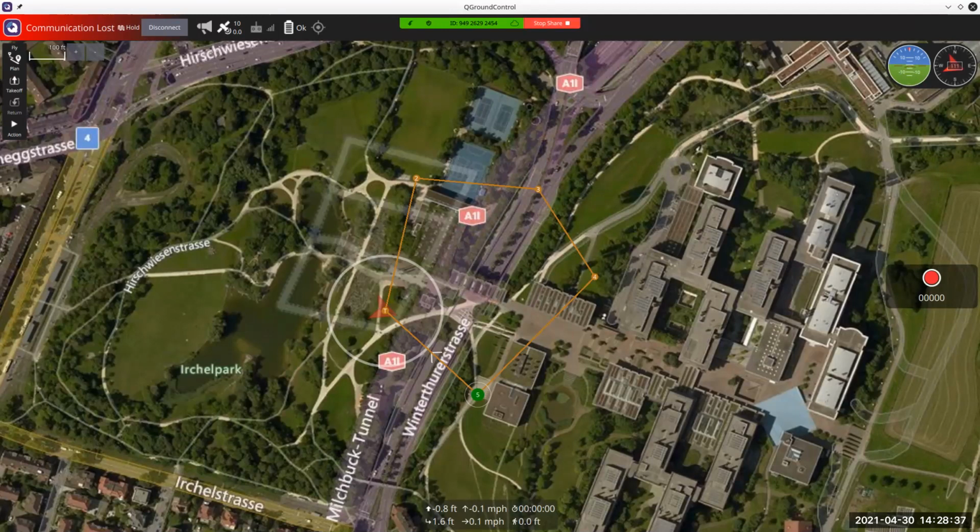So just to validate here, and again, Garrett, what we try to do is create not just a simulation environment that can run a vehicle utilizing a model of the Leapfrog vehicle with the appropriate parameters of mass, the thrust levels, and the thrust of the attitude control system, but also the ability to insert a guidance control algorithm that allows you to tune potentially changing gains if you're using that type of controller, such that you can test the vehicle's stability, operate it, and develop it. And the real challenge is not just to take off and be stable and look great, but to begin to move and follow a particular pattern.